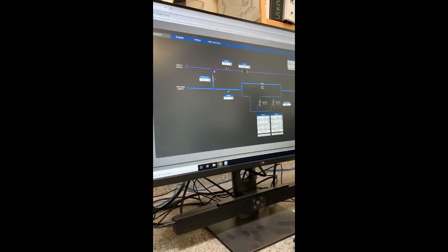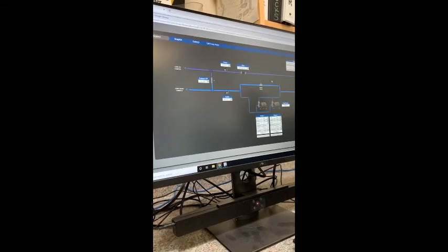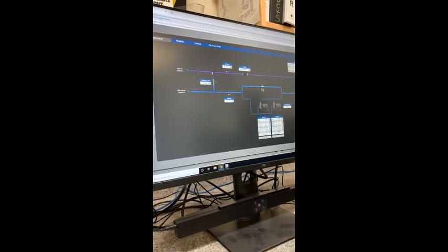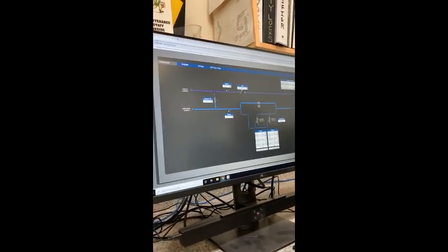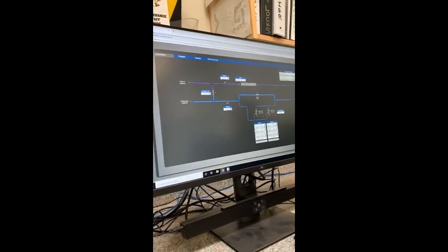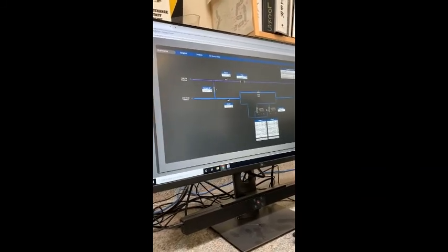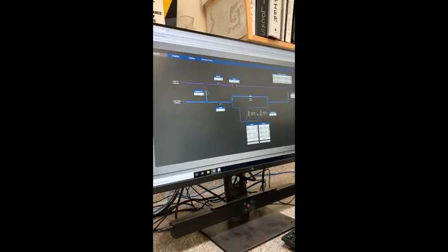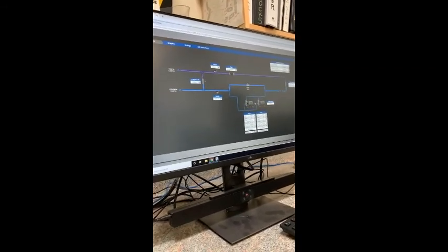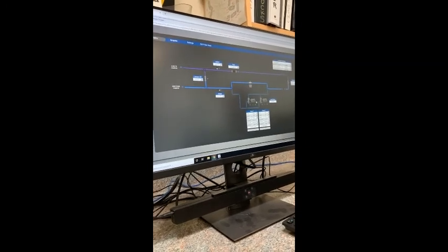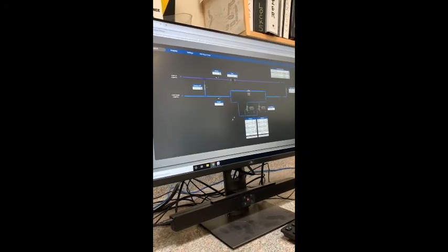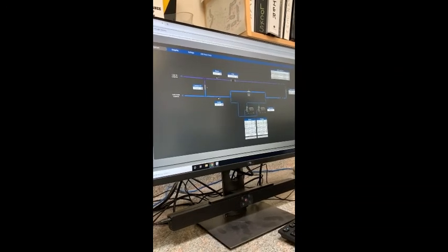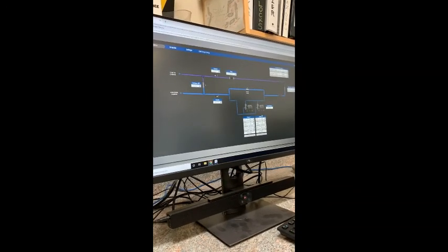So basically, this is kind of just an overview of the system: the differential pressure coming from the campus, the supply and return temperatures, how much water is actually flowing through the system. This is chilled water for just one of the buildings. Each building has its exact same setup. This is for the building we were just in. It has chilled water that's supplied by the campus. It comes into us and goes through pumps, or it doesn't always go through pumps. The booster pumps are in parallel with the check valve, and they'll only come on if needed.